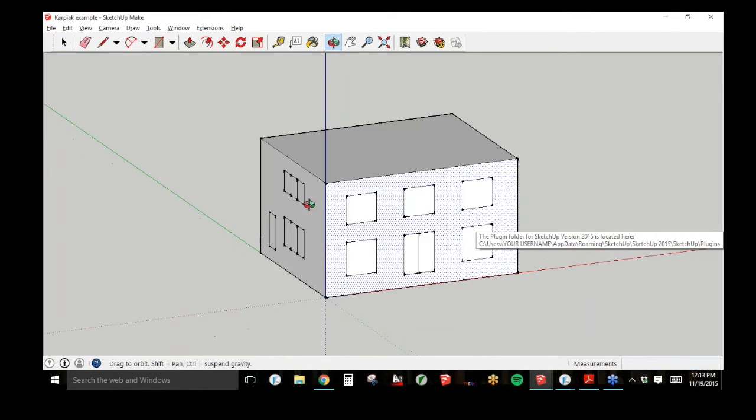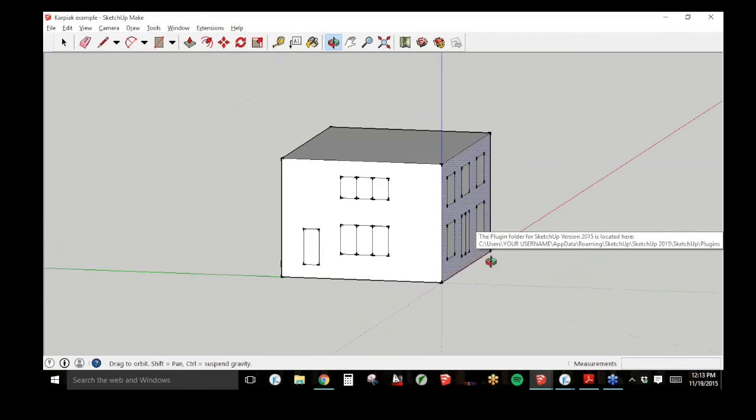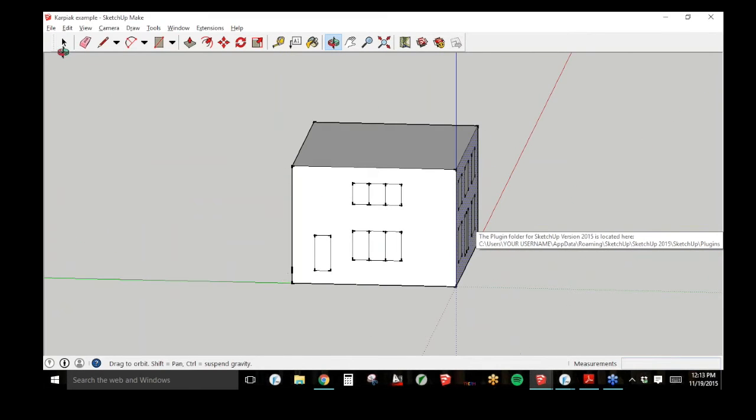This is drawn to the exterior of the thermal envelope. So what that means is this wall is drawn here. This exterior boundary is the exterior of the wall insulation. So that would be right before a rain screen, depending on your facade there, wherever the thermal envelope ends. So this is the exterior of the wall insulation, or the exterior of the thermal envelope, thermal boundary. This is the under slab insulation, so the bottom of the under slab insulation. So you can see it's pretty far from that door there, so there's probably a slab and then insulation. And this is the top of the attic insulation.